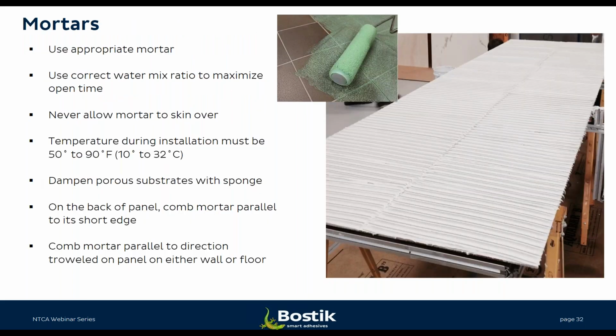So with these types of mortars, you want to make sure that you're using an appropriate mortar, a mortar that's been approved by manufacturers for this type of use. Follow the correct water mix ratio, and make sure that you never allow the mortar to skin over. Doing so would result in a bond issue. So follow the temperature during installation ranges. Generally, these are called out from 50 to 90.